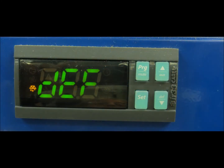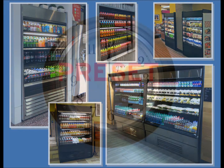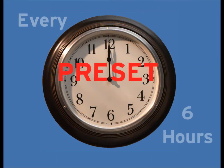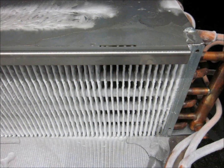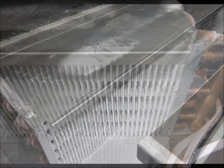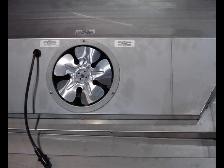When the unit is in defrost mode, the controller will show DEF with a small snowflake. Our refrigerated display cases are preset to defrost every 6 hours, which is initiated by a time-based clock. The length of the defrost cycle is determined by how much ice is on the evaporator coil. The fans will still run while the case is in defrosting mode.